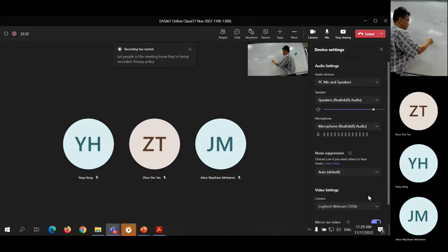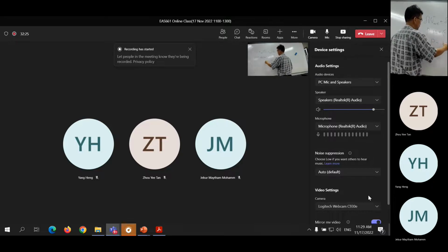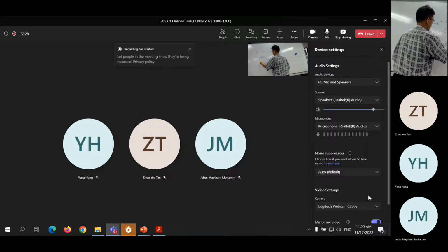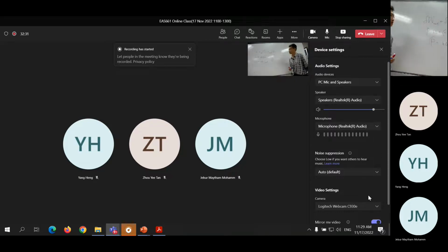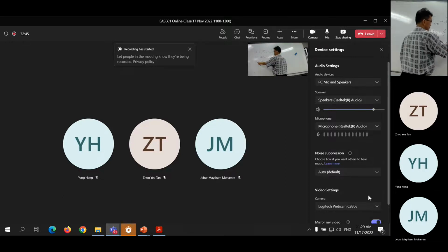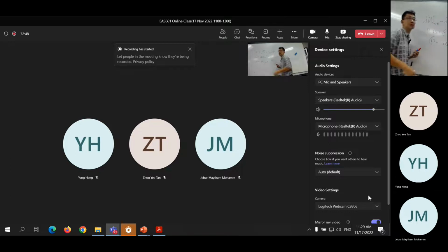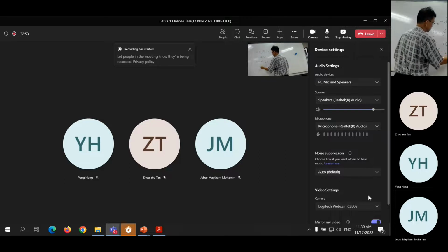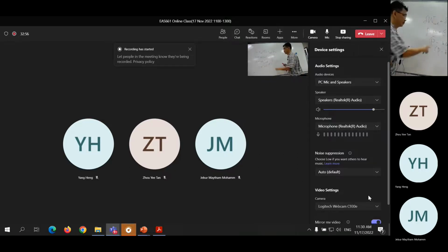So we can then take this minus K delta, go to this. So here, this multiplied with this, and this is virtual displacement. So for this to be valid, this multiplied must be equal to 0, and this can be any value. So this must be equal to 0. Okay. So from here, you get P is equal to K delta,